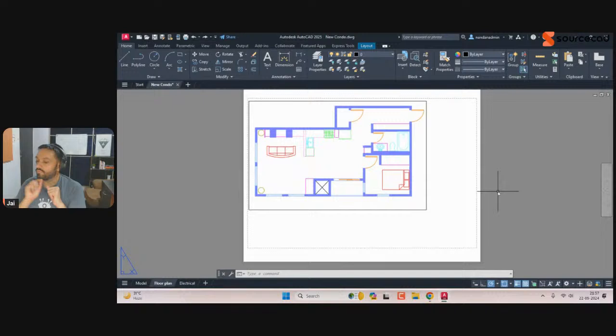All right. Once again, so far, is everything clear? Oh, yes, the flattened text. That was, again, a question from Vineet. The flattened text option was exactly just that. The last checkbox, remember in the publish option, convert text into geometry. That's what you can select to flatten the text.